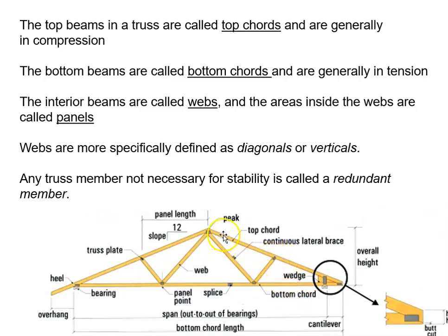So in a truss like this, I would expect all of these web pieces to be working here, but in some larger trusses, perhaps, depending on the configuration and the bearing and the load requirements, some of them might not actually be structurally doing any work.